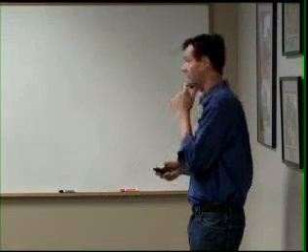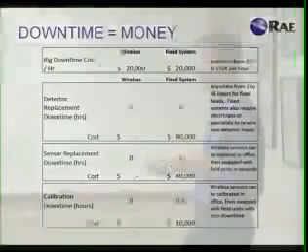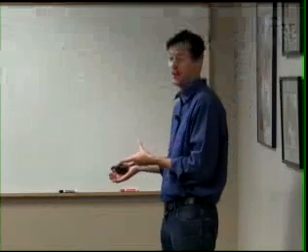And then finally, it's the same thing with calibration. So calibration is just a required part of accurate gas detection. So typically when you're calibrating a fixed system, there's usually a mode on the detector where it allows you to tell it that you're going to calibration mode, or you have somebody at the controller disabling the relays, the alarm settings while you're calibrating. So in essence, you still have to shut down your system. You're not actively monitoring the safety while you're calibrating. So there's a downtime associated with that calibration. And again, on the wireless side, you don't have to do that. You can calibrate in your office with a spare detector.